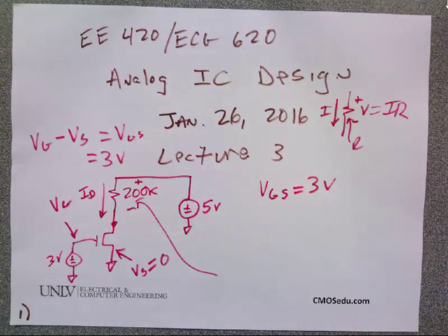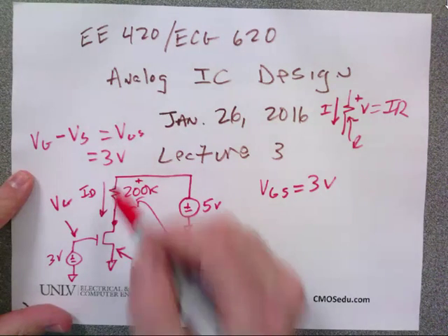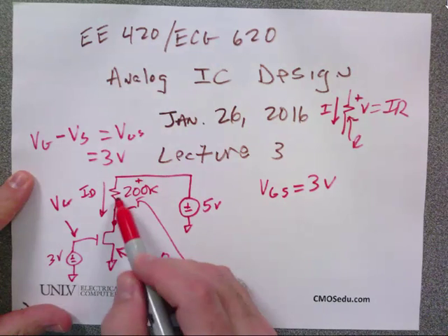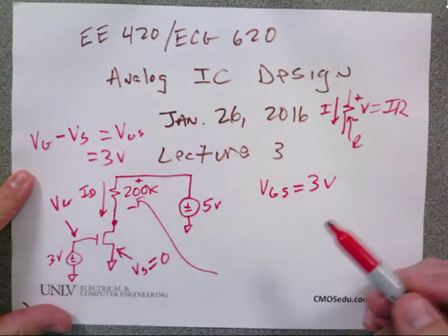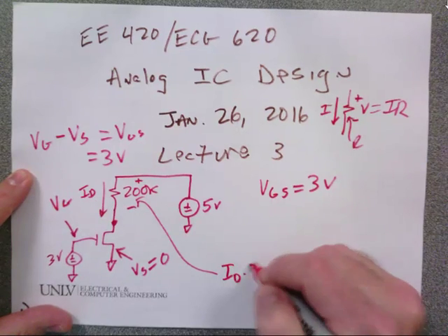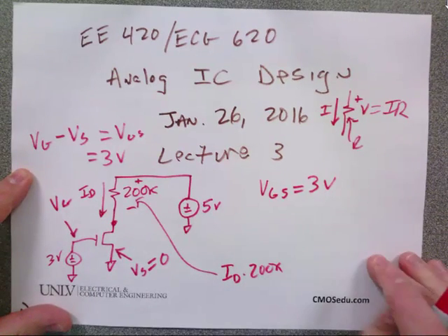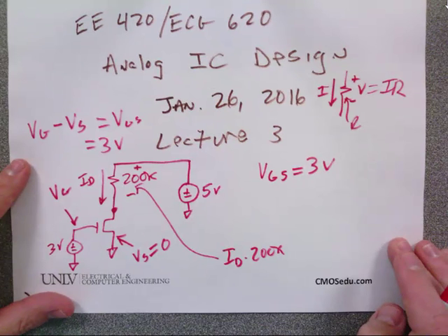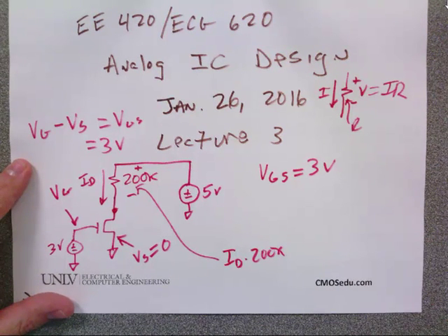I'm not going to quiz you or do anything complicated. Stop making it hard. Okay? Everybody see. Now I'm going to ask one more time. What is the voltage drop across the 200K in terms of ID? Anybody not follow that? Is anybody confused about how a current flowing through a resistor gives a voltage drop of I times R?